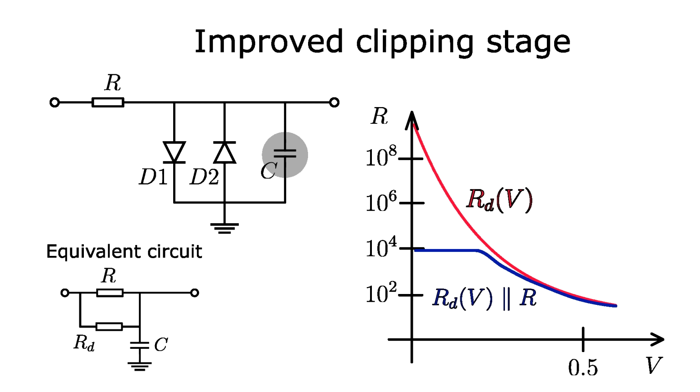As a result, we have a dynamic filter that attenuates many high harmonics when distortion is high, and only attenuates a small portion of high frequencies when distortion is low. This means that the filter's cutoff frequency adjusts itself based on the amount of distortion, resulting in a more tight-sounding effect. We only determine the order of the elements' values based on the desired frequency response.